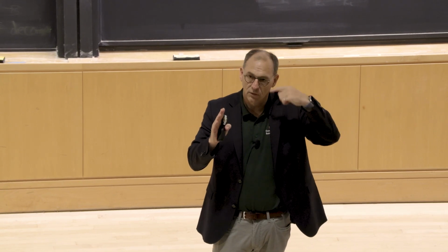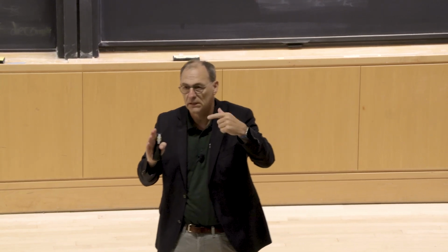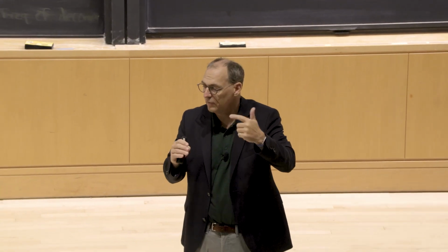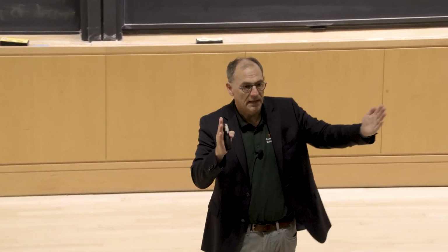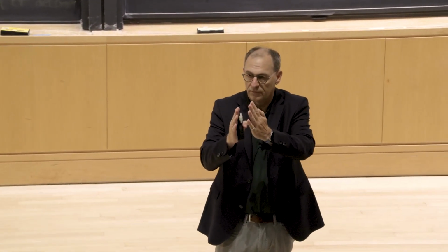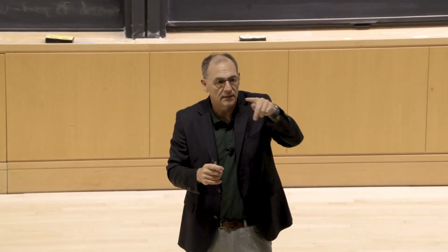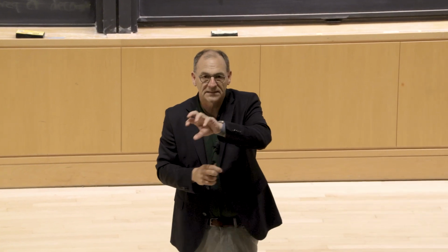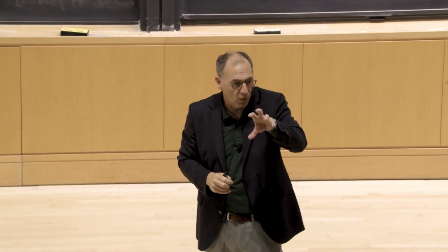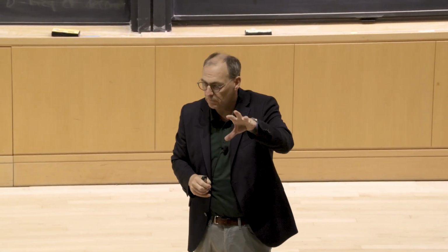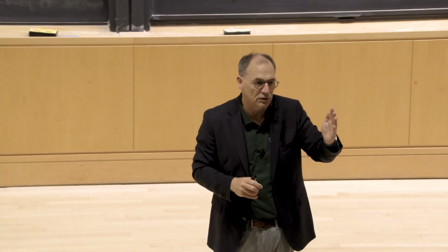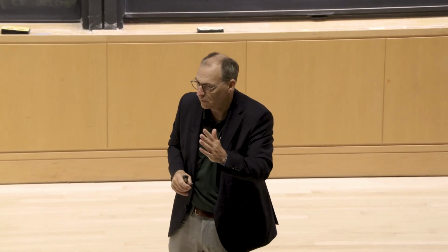And now, going back to the nonlinear feedback we talked about yesterday, if this pressure wave is exactly in phase with the lean and rich pockets, then the next rich pocket you get is a little more rich, and the next one is yet more rich. It gives you a stronger pressure wave, and it makes the effect even stronger, okay?